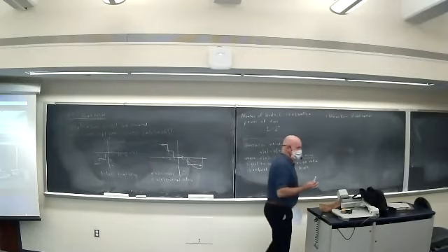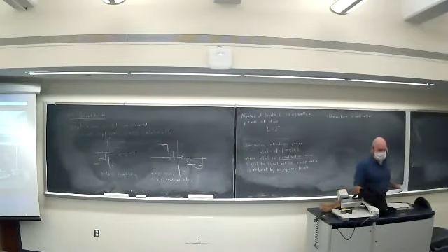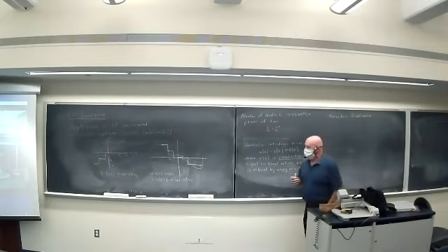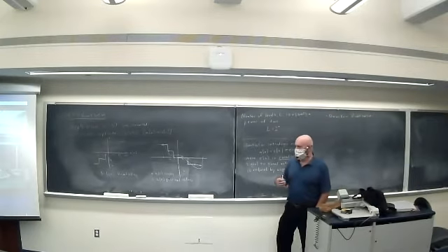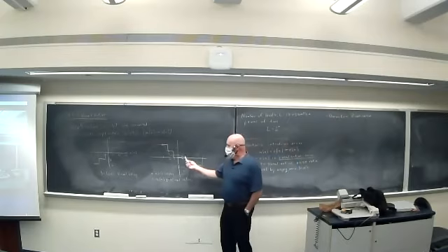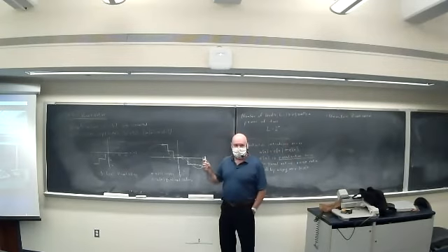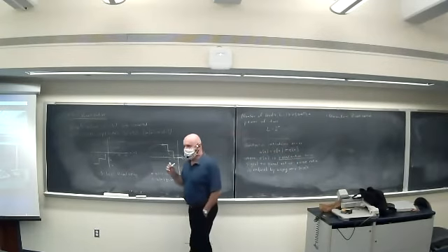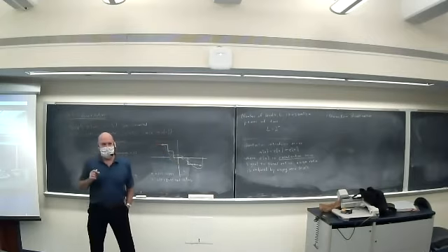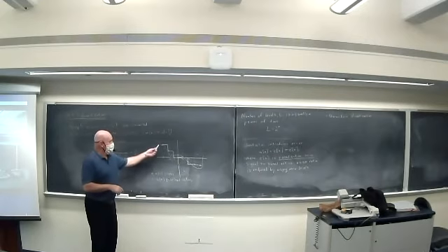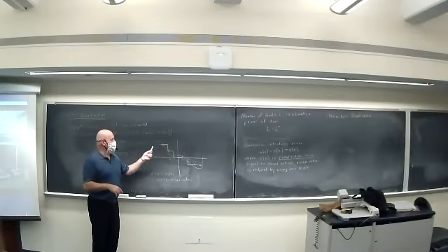Seems like the reasonable thing to do. Why would you ever want to use non-uniform quantization? Well, the reason has to do with the fact that in audio, the ear tends to be more sensitive to smaller amplitude, lower volume signals than larger amplitude signals. You can't detect the quantization noise as easily.